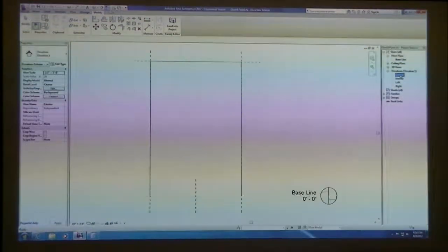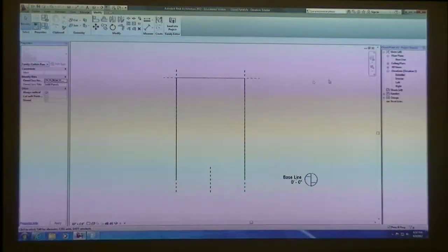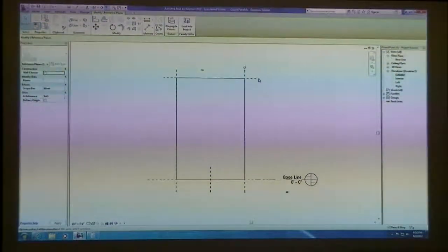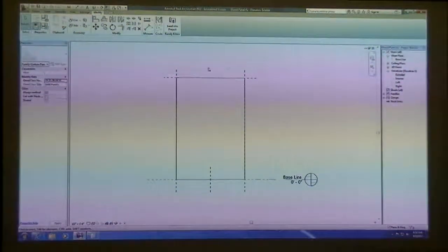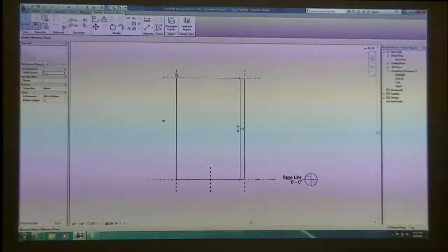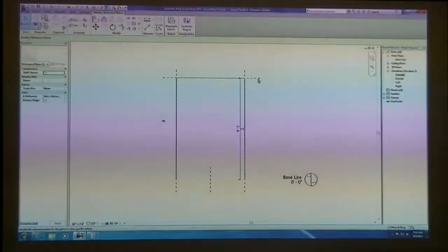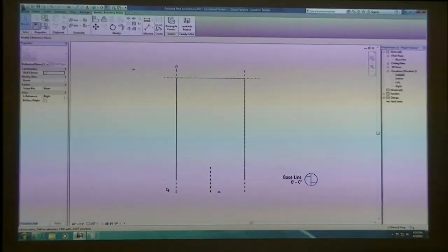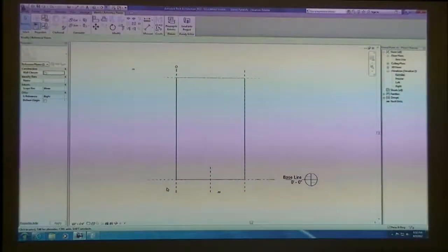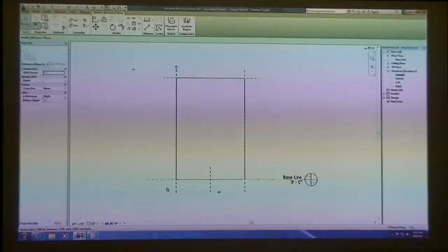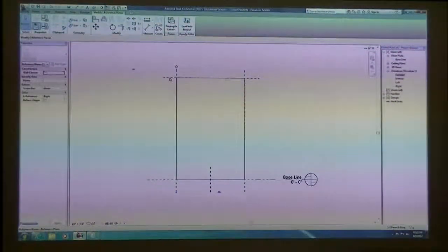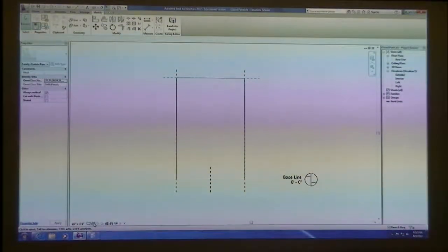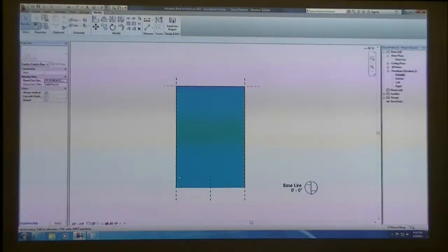If we look at the exterior view, you'll just see in elevation a couple of reference lines, and there's no parameters set to any of these lines. But in this template, this is set up so that this sheet of glass is going to expand to the grid lines of your curtain wall panel system. So whenever you divided up your curtain grid, this is how the glass knows to stretch to that reference plane. And this will come in handy in a little bit when we have to manipulate this a little bit further.